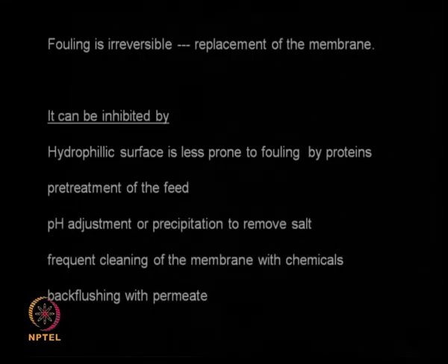filtration process, it gets slowed down and slowed down, and after some time it is not very efficient to run your membrane, so you need to stop and remove all the fouling, or if it is irreversible you need to completely change your membrane. So that becomes very expensive, changing a membrane is very expensive because most of the cost is the cost of the membrane.